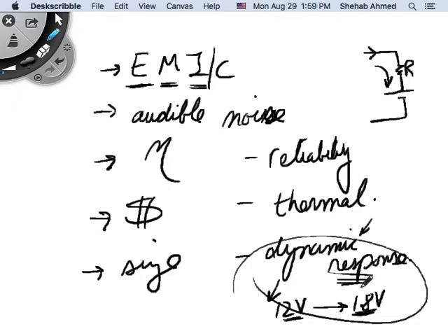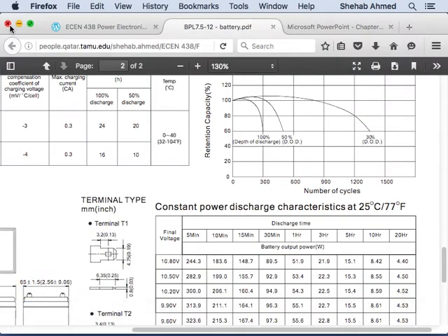So we actually study this, and you will design converters knowing that this is the dynamic performance based on the switches that I've chosen, and the capacitors and inductors that I've chosen. I decide what the power converter dynamic response is. Which means that you cannot design a 1.8 volt converter for a battery charging application, and somebody takes it and tries to use it to run a processor, and it won't work. Of course it won't work, because you have not designed it to operate dynamically for such a load. So things like that we will discuss in the course. Okay, so now this was the introduction.